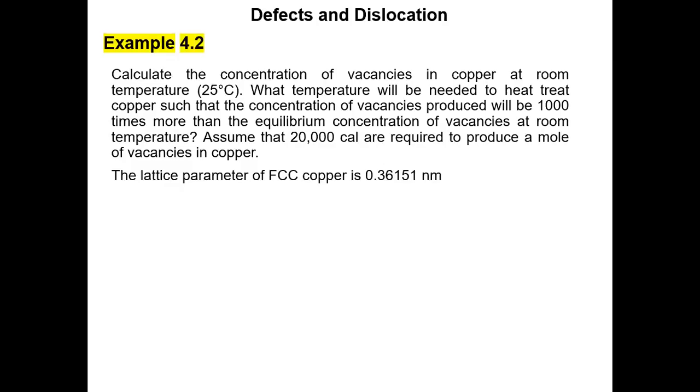What temperature will be needed to heat treat copper such that the concentration of vacancies produced will be 1000 times more than the equilibrium concentration of vacancies at room temperature? Assume that 20,000 calories are required to produce a mole of vacancies in copper. The lattice parameter of FCC copper is 0.36151 nanometer.